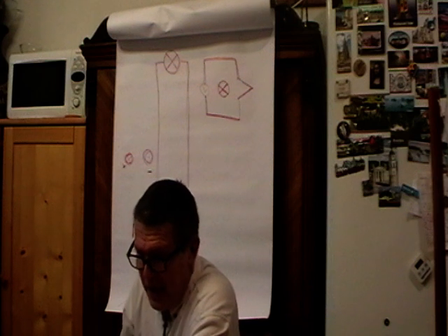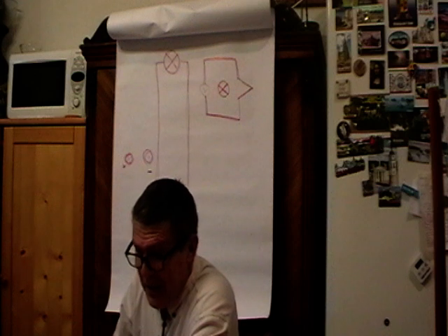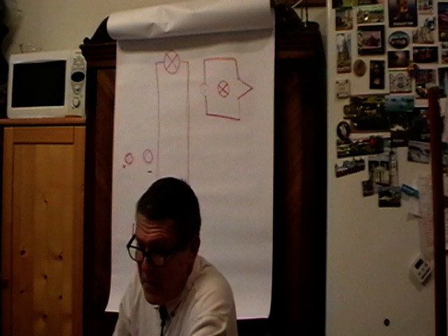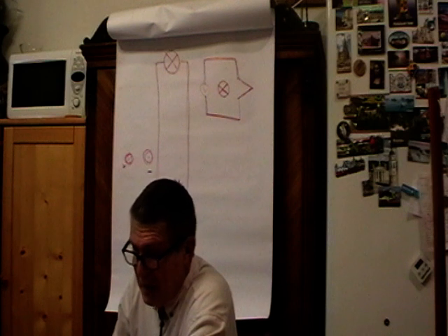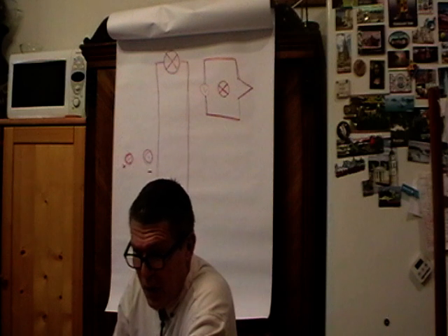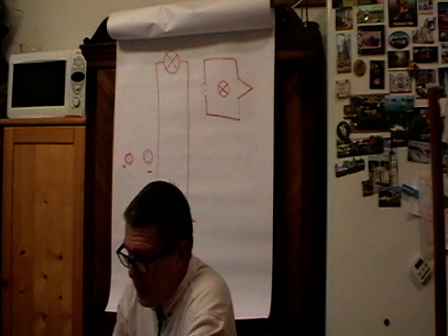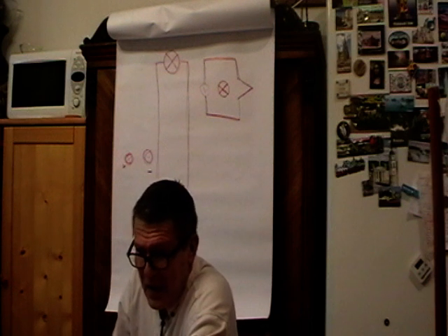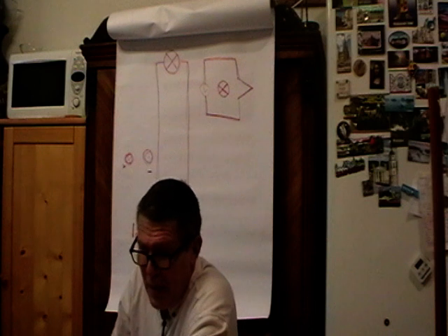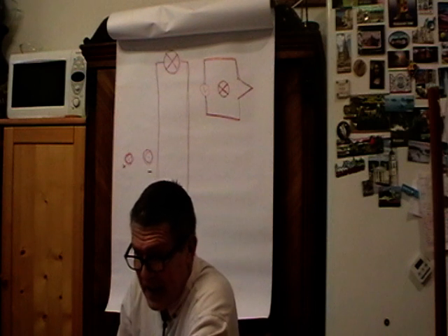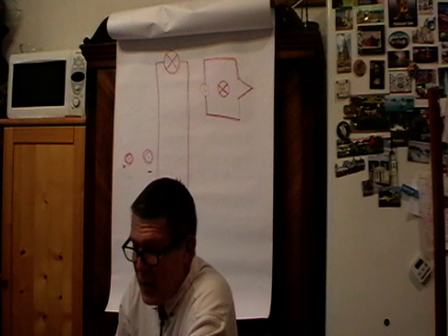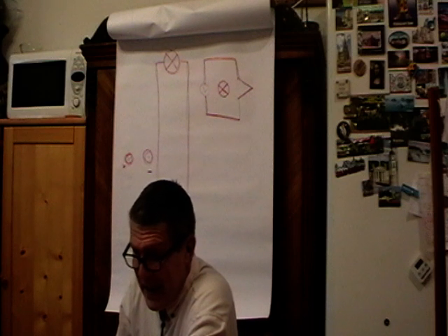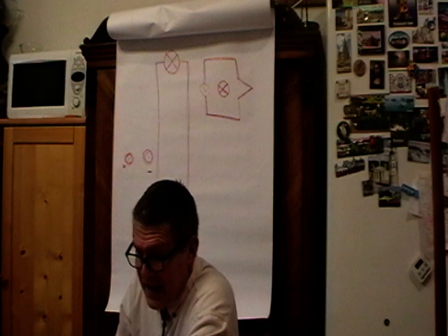Well, we have 3,000 kilometers wavelength, and that means that we have that problem at a very long transmission line, which goes, for example, from Europe to the end of Kamchatka. There is no direct line through the Mediterranean Sea, but if you have a cable from Europe to America, or from Europe to Africa, it could be that you have to consider this, which is strange for DC circuits.